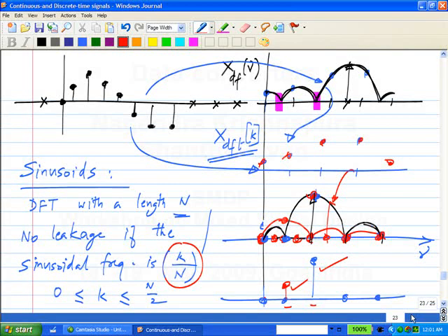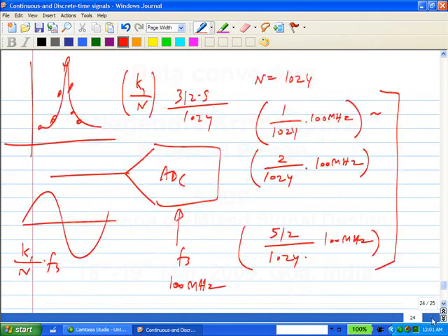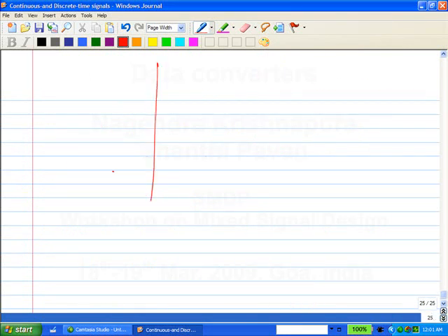And your ADC could have other frequency components, as you will see with the oversampled case. Although probably most of you don't know about the oversampled case, I'll just give you an example. If you look at the ideal spectral density of the oversampled case, it should have your signal and then noise which rises like this. What will happen with leakage here?